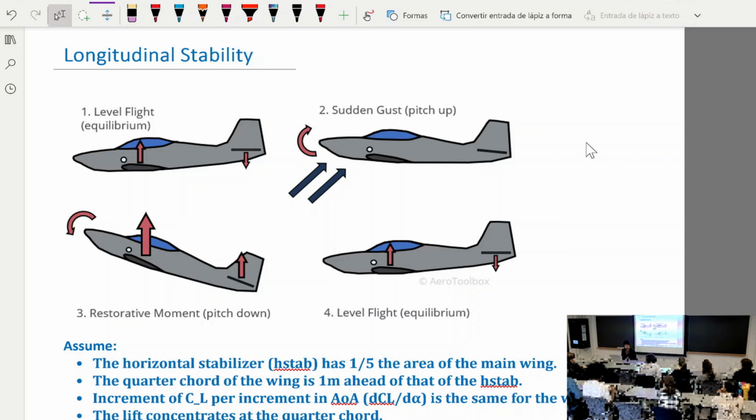I don't know exactly what you covered in Unified, but you might be able to design everything without thinking anything about the vortices. And the effect of induced flow really comes into the picture when you have an airplane that no longer has a very large aspect ratio, or you want to design everything to very high precision, right? So when you are making an airplane that's large and potentially carrying people, instead of an airplane just for fun, you then have to start considering all the effects that might be small. And we'll see in other cases, if you have an unconventional design, you have to consider the induced flow, even if you design something for fun.